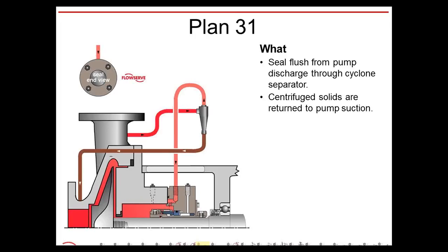Over time, the cyclone separator will wear out. So as soon as you put it in service, it works fine. Over time, it's slowly going to wear itself out. Now you have to check and make sure that the cyclone separator isn't failing, because otherwise it's worthless when they're out of spec.